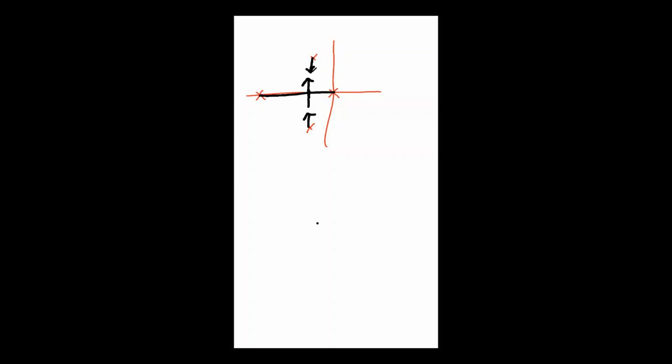Now, if you see, both of these branches will intersect at some point. So you need to calculate this point also, this breakaway point, which we have calculated. Again, if you see in the notes, we have calculated 3 breakaway points. If you turn the pages, we have calculated 3 breakaway points. S1 was minus 2, and S2 and S3 were minus 2 plus minus j 2.45 or 2.46. This was our second point. So this is minus 2, and this is j 2.46.